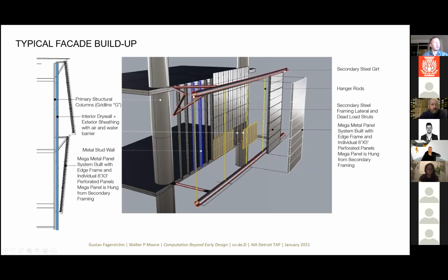that are at the level of the slab edges, which is then where the sheathing and the waterproofing and the insulation will be attached. So the assembly logic of this is like a curtain wall. If you're familiar with how those work, they are usually top hung. So you have your gravity connection at the top, and then you have a lateral pin only at the bottom.